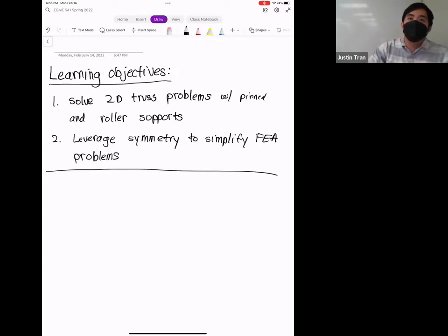So do you remember 2B? Vaguely. For the first part, you would just set up the spring stiffness matrix, right? Yep. And at node 2, you have a spring connected to a truss, so you use just the truss equations in that one? Yep. And then you just keep going down the line and combine with the global. At node 2, you'd have a stiffness matrix for a spring and a stiffness matrix for a truss, and you just add them together. Okay, not nearly as hard as I thought.